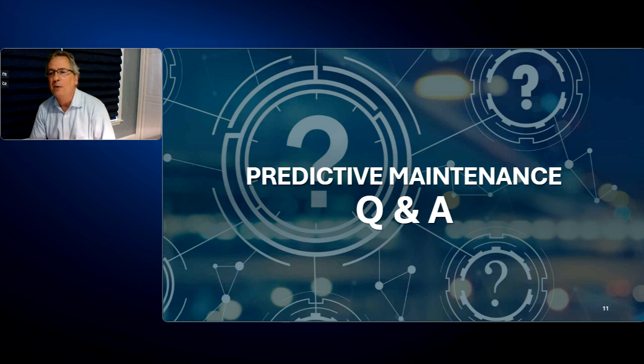Adrienne Temple. When I was in manufacturing, I assume that means you're not in there anymore, I found out that some of our technicians were not capturing the actual failure code. So they were capturing what they did as part of the routine maintenance when they pulled that piece of maintenance. So that's a great piece of learning for people. We have to distinguish problem from cause or failure. Otherwise, the database won't give us the information that we need.